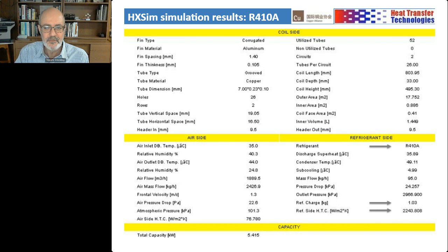It is very popular in many parts of the world, especially in the Far East and even in equipment in the U.S. Companies like Daikin and Goodman use 5mm tube in many of their applications, air conditioners and appliances, and many others are looking at that. There are no more constraints from an equipment point of view. The process is very similar to larger tubes once you have the equipment in. And the expanders. There are also new types of expanders that have been developed specifically for small diameter tubes that are not using mechanical bullet expansion, but actually pressure expansion. Those are available from companies like Burr Oak and others. So you have options now. If you want a mechanical expansion or you want pressure expansion, you can choose between the two.